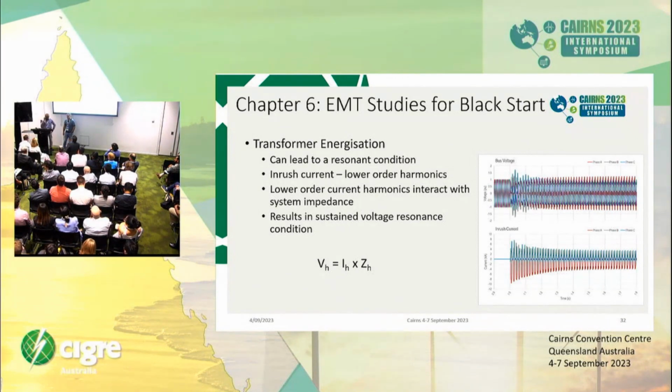It's a very good question. Honestly, there are no slides on that part here because we confined ourselves to the traditional studies. But if you are really using your DRs in the restoration process, definitely it will be a big challenge to model them correctly and include them in the restoration studies, because some of them may not have good models to represent them. Even if you have good models, there are so many numbers in different places, and combined with this, the study will be challenging.